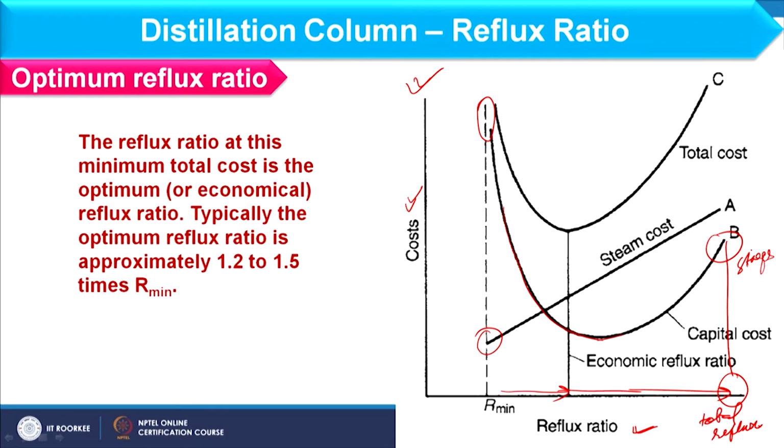However, at that time the reboiler and condenser duty will not be less, that will be maximum. So, in that case the capital cost of the reboiler as well as condenser will dominate, and so you can find that the increment in capital investment, if this were based on number of stages only, should be like this, right. However, here it is increased, which is due to the capital investment of reboiler as well as condenser. So, in this way we can consider the capital investment.